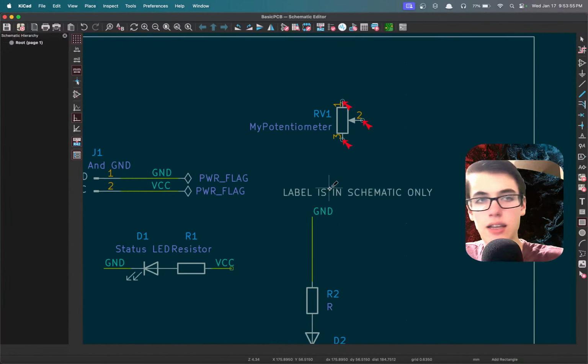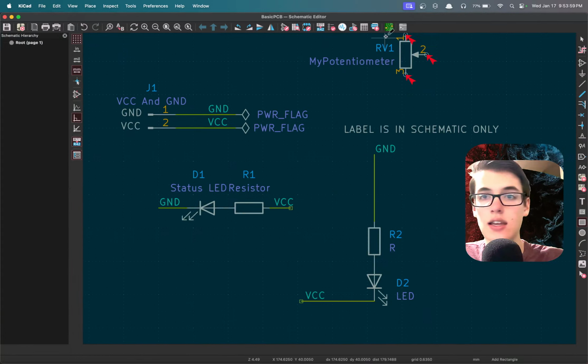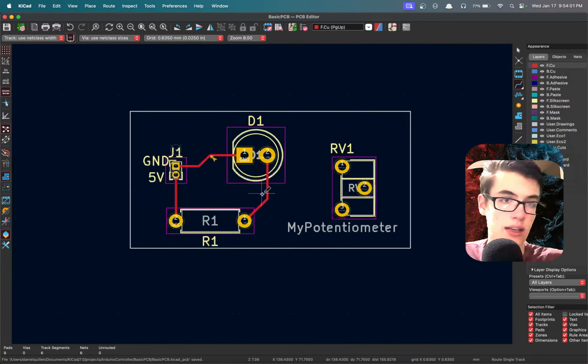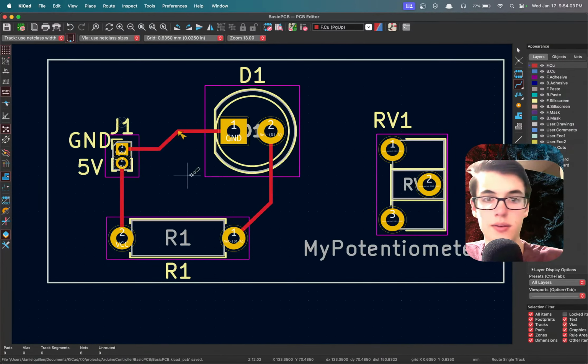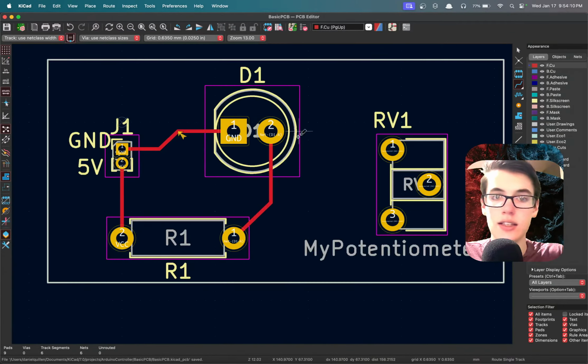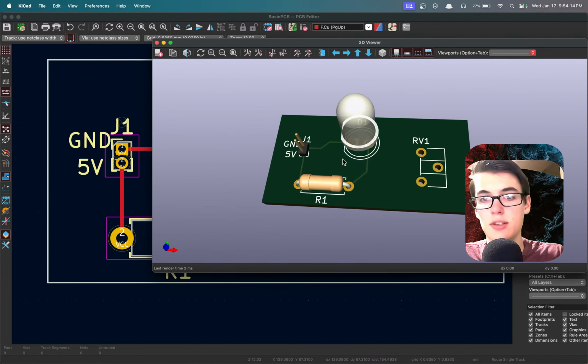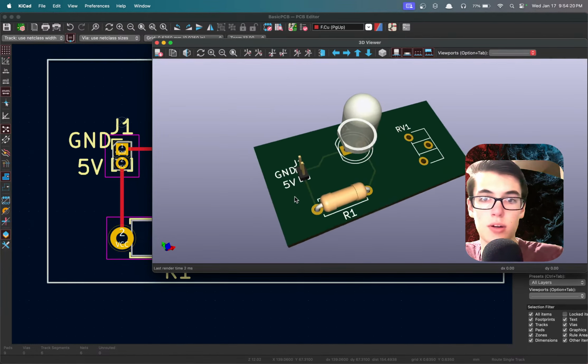That's about it for a very basic intro to KiCad, and you've already created a simple circuit model that has 2 pins that connect to an LED, and this thing would work if you had this manufactured. You put in a resistor, put in an LED, put in these pins, you connect the wires up to it, and this PCB would work perfectly well.